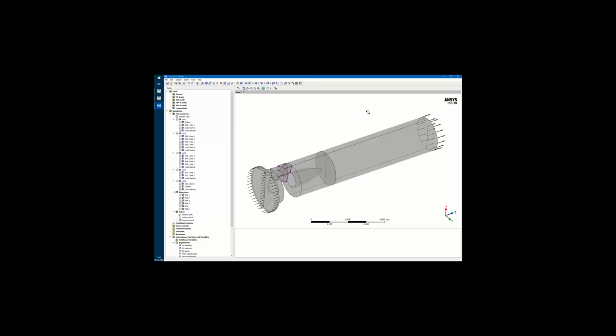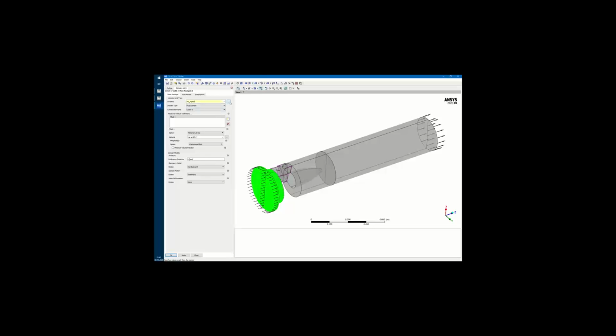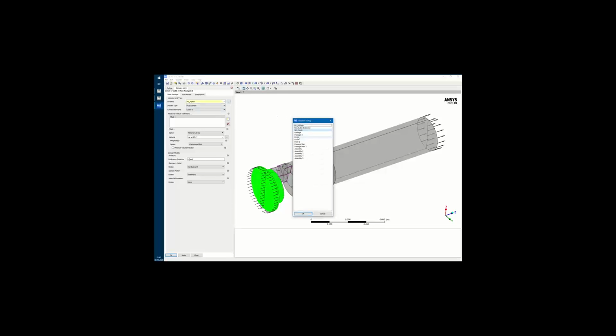And as I mentioned, named selections are created automatically for your turbomachinery components. And you can use them inside of Ansys Meshing, CFX-Pre, as well as CFD-Post to apply your settings in a comfortable and more robust way. So, for example, in CFX-Pre, I have used them to set up my fluid domains. Normally you would need to deal with these artificial IDs if you haven't set up named selections manually.